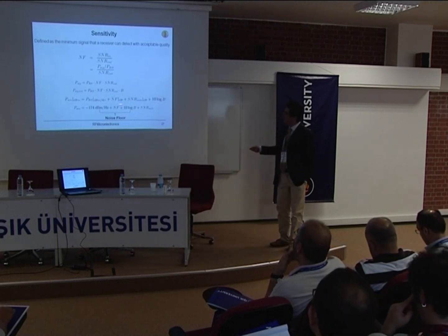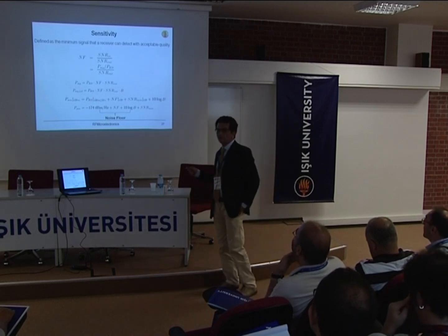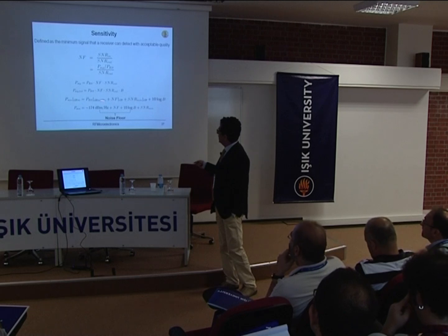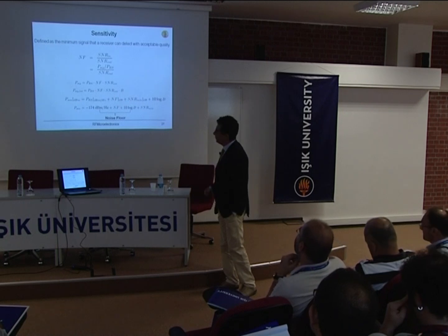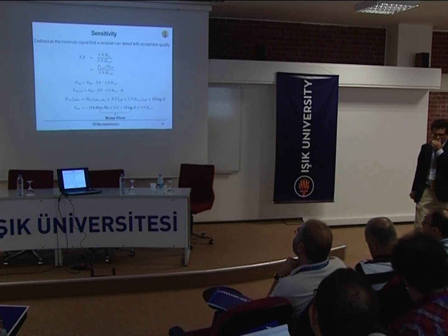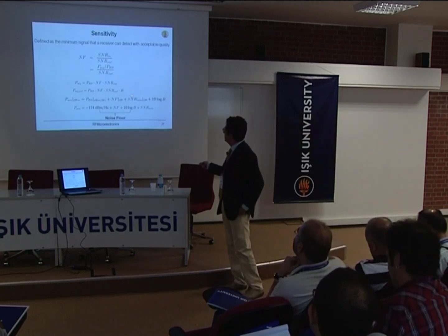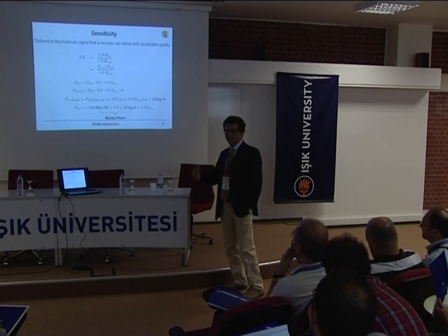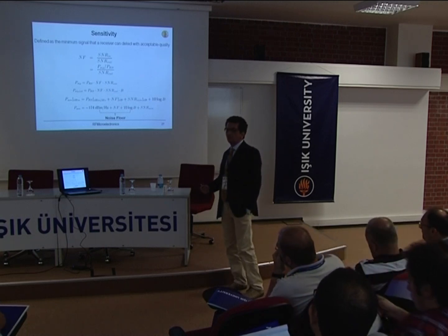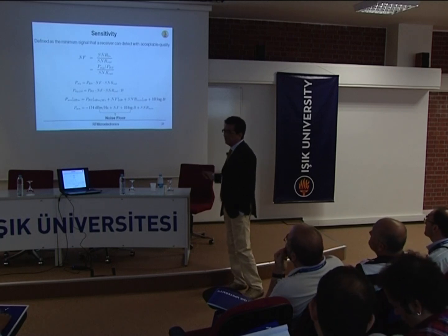So this is a very interesting equation because it tells us what is, for example, the sensitivity of a signal once we know the minimum signal to noise ratio, which translates in other terms in the maximum noise figure we can tolerate from a receiver. So let's look in another way. We, for example, know that the application we're interested in requires a given signal to noise ratio to elaborate the signal through the processor with a given bit error rate. So we know from the specs what is the signal to noise ratio.